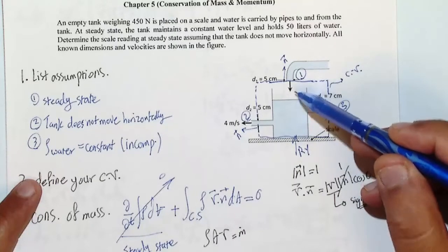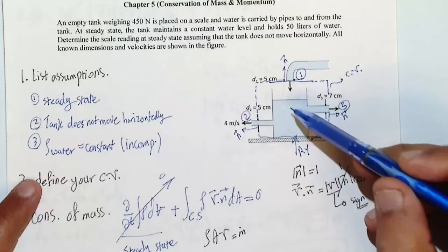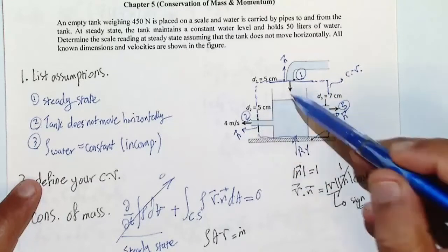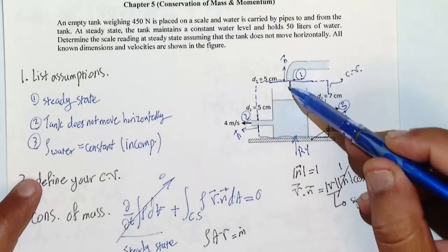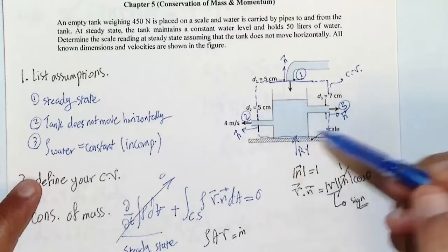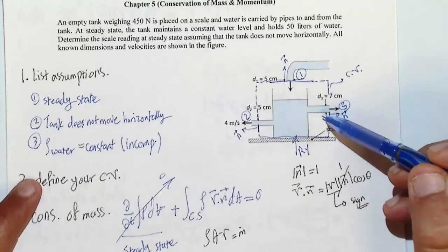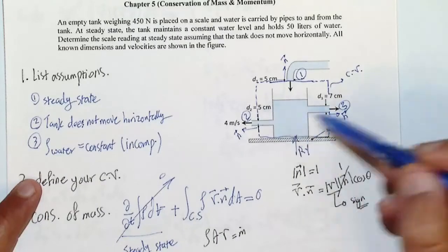Okay, so you need conservation of mass. To do conservation of mass, you have to make the output equal to input. But again, you will find out that V2 is given, but V3 is also not given. So it guided you to apply conservation of momentum in x direction as well.